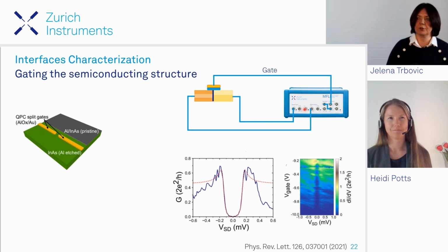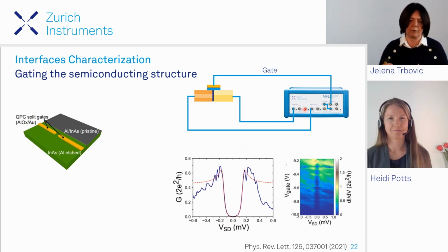So I think Heidi will show a little bit later how you can actually see how much noise you have, whether you have the 2 omega component. So you can set your measurements properly, but maybe start off with a factor of 10 for the frequency, or if you know the time constant, you can also start off with that and convert into bandwidth.